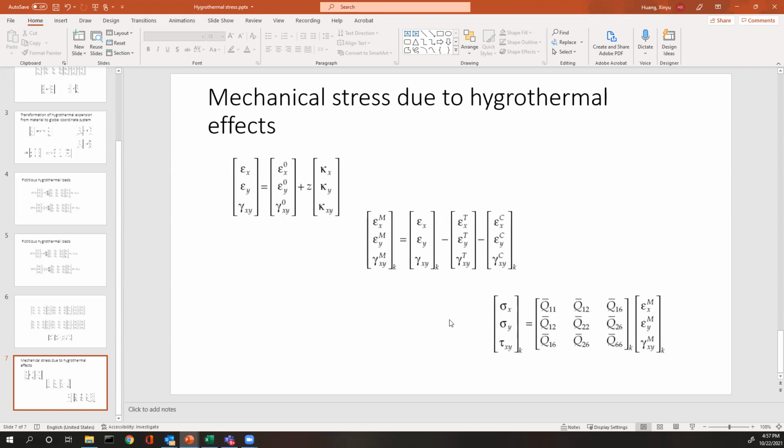Yes. For the homework that you sent me today, you want to describe the patterns. When you have a symmetric layup, when you have a quasi-isotropic layup, the ABD has patterns, where certain terms are zero. You want to describe those patterns. You can find those patterns out by experimenting. You put in a symmetric laminate, you look at which terms are zeros in ABD.